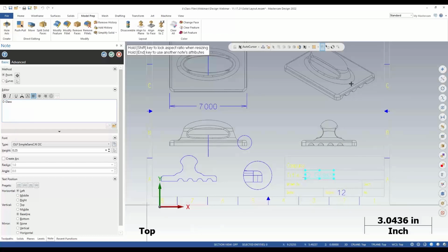In some solids, when you import them in from a different CAD source, while they may appear to be red or green or purple or whatever color that they come in as, that information may have been mistranslated to Mastercam as saying, hey, you have put a coat of paint on top of the model, but underneath that paint, that model is still gray, which might be what you're running into, Elliot. But again, just give us a ring afterwards and we can take a closer look.